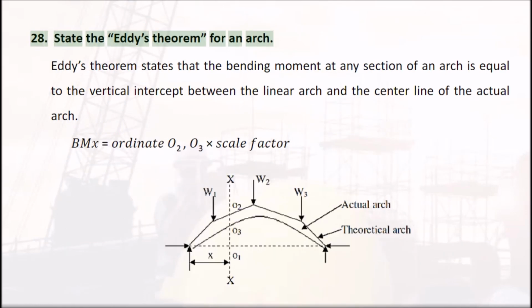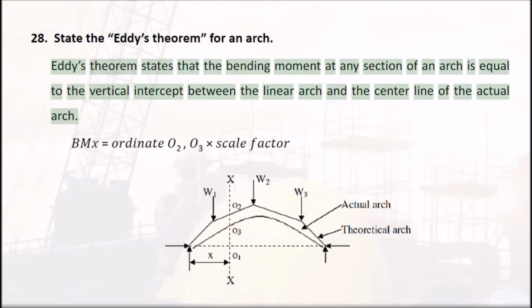State Eddy's theorem for an arch. Eddy's theorem states that the bending moment at any section of an arch is equal to the vertical intercept between the linear arch and the center line of the actual arch.